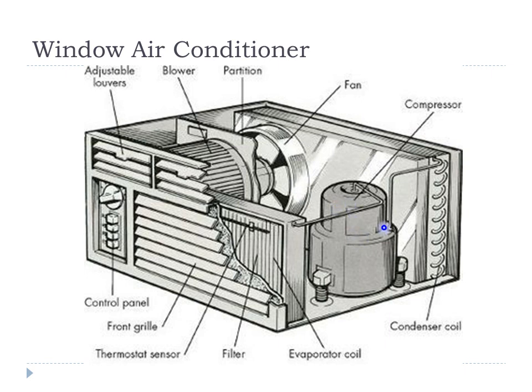Then from the compressor you have a condenser coil where the refrigerant is taken to get cooled, and from the condenser we have a capillary tube, which is not visible over here, but this capillary tube is there to get expansion of the refrigerant.